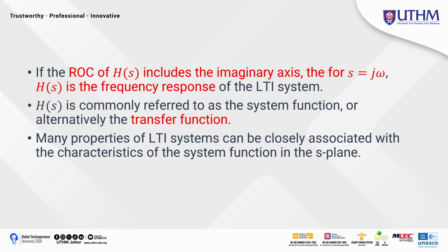There are many important properties of the LTI system that can be closely associated with the characteristics of the system function in the s-plane, such as the stability, frequency response, transient behavior, and physical realizability. All these can be directly determined by the location of the poles and the zeros of H(s) in the s-plane.